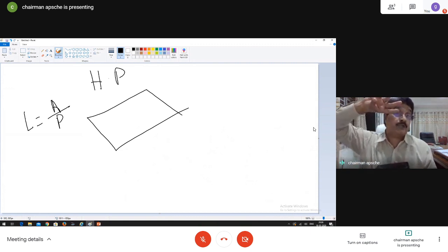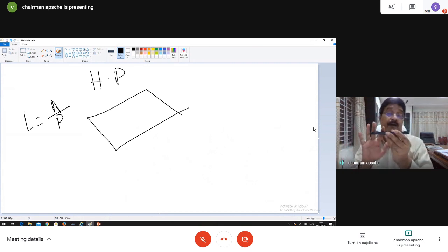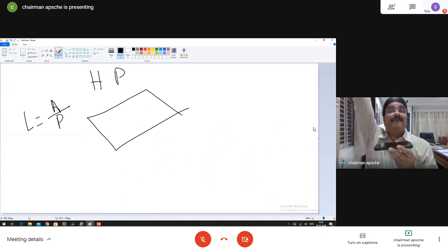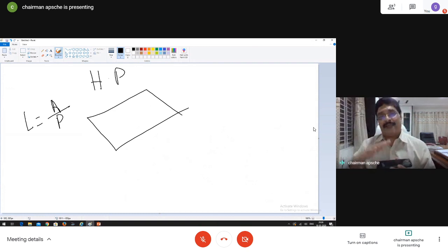But the so-called natural convection, if the plate were to be hot, now what happened? The colder molecule came, acquired the heat, increased the temperature, density is reduced, quickly it was going away. But here it cannot go away. It all settles here. So, for a horizontal plate with the hot top surface, there is a favorable condition. The second case I have explained is highly unfavorable. What do I mean by highly unfavorable? Convection is not happening. The colder molecule is not capable of moving up. So convection is not happening.